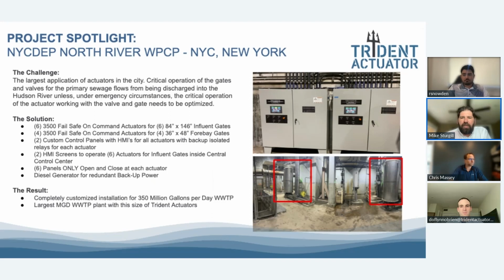These are the same panels I talked about. We do have panels at the gate. You can't see it in this picture, but there are explosion-proof panels to operate. In this application, there are actually 3 spots to operate the actuators. Here or there in their control room, they have an HMI setup. And then, like I said, down at the actuator level, there's an explosion-proof panel. So as I said, this is one of our largest single installs, at 350 million gallons a day that we're protecting in that wastewater treatment plant.